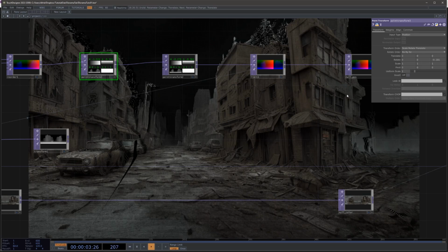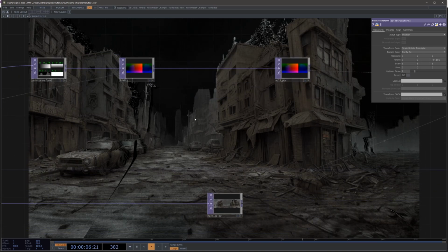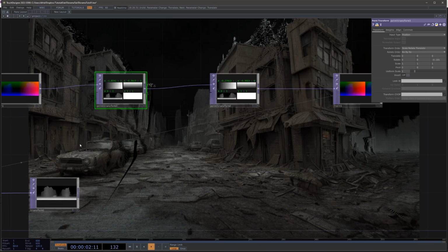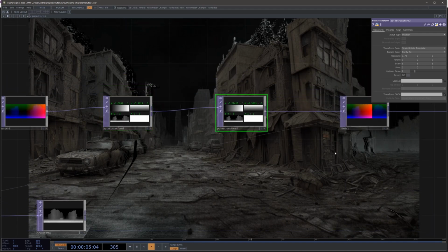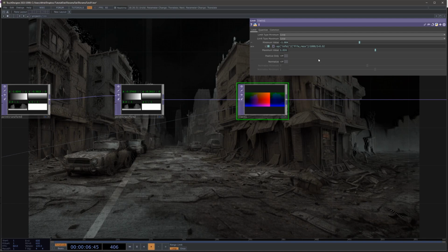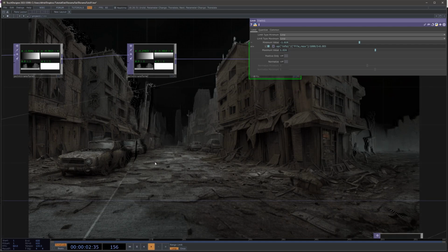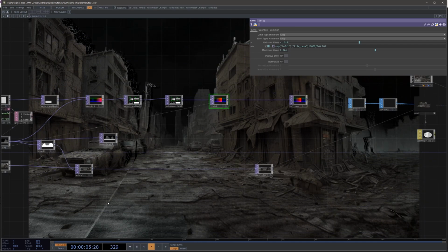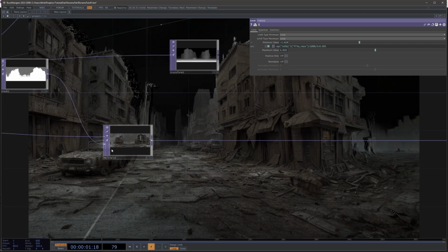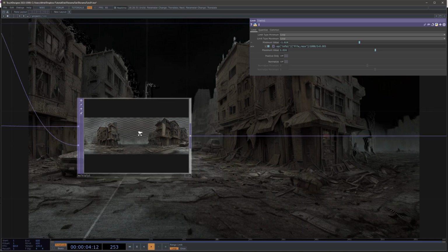So there is a way you can correct it a bit, but what we can do as well is to have it overlap just a bit, so we won't see this gap much, or at least a bit less. For that we can correct this in the limit. In the minimum value we can add plus 0.02, and now it's overlapping maybe too much, so let's say 0.05, and yeah, now I think it's a bit better. The thing is now the colors are adding as well, which is not really great, but we can maybe correct this in the color part.